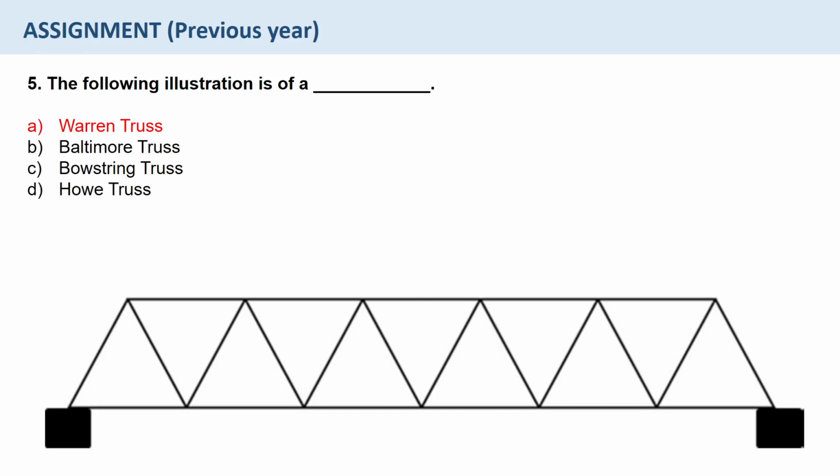So the answer is that Shenzhen Universiade Sports Center in China is an example of folded plate structures. Now, why? Going back to the image, you can see that these are slabs which have been joined together in inclined ways, and this is how it looks. So this is not an arch, not a dome for sure, and not a pneumatic structure. It is a folded plate structure.